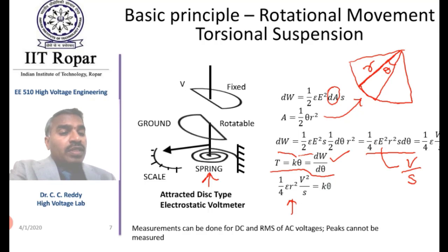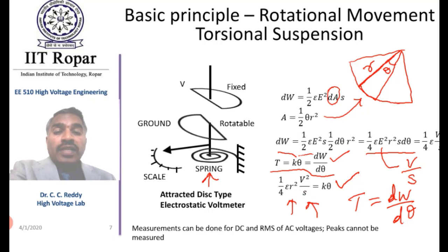So torque is equal to dW by d theta, this you remember, in magnitude. So equating that, we will get like this. Here on this side, unlike the previous case, you have S minus X. Here we will not get S minus theta because S is fixed. And this theta is given by the stable value of theta. This theta is a small incremental theta, please remember.